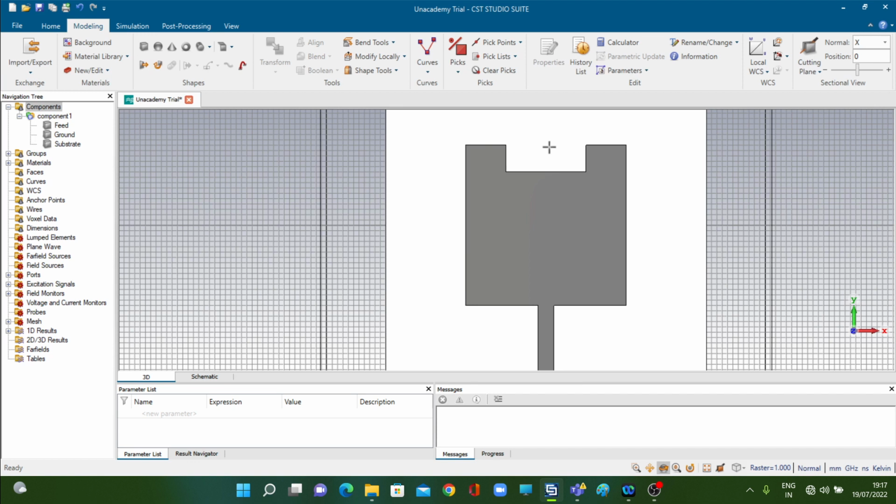Similarly, Koch snowflake is a hybrid type of fractal. It is neither square nor triangular. It is hybrid shaped. Okay, so these are of complex natures. So as for now, we will be concentrating on generating this Hilbert fractal only. From a rectangular patch, we will cut out rectangular slots only to generate a Hilbert fractal shape. The first slot we have actually cut out like this, which you see in front of you.